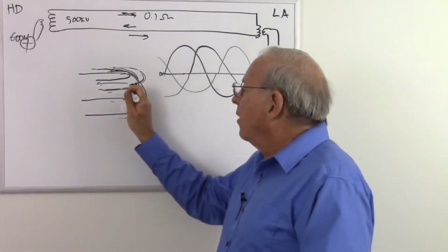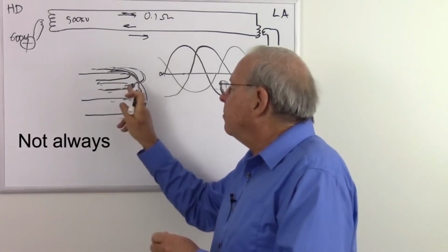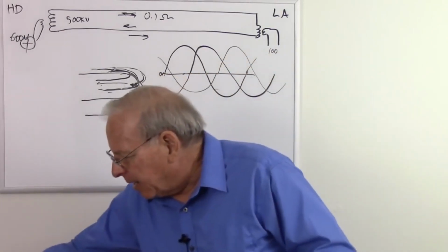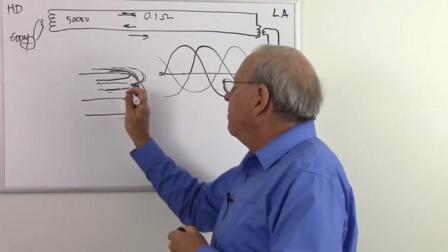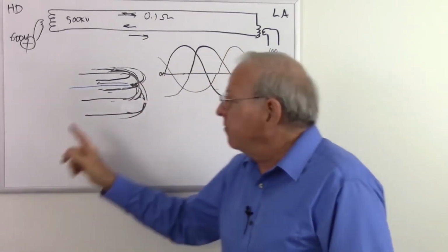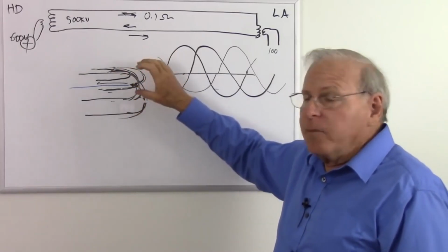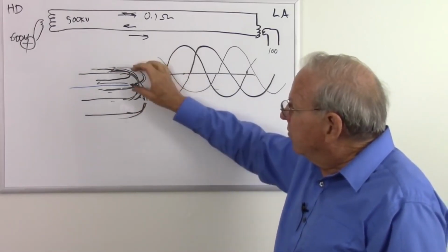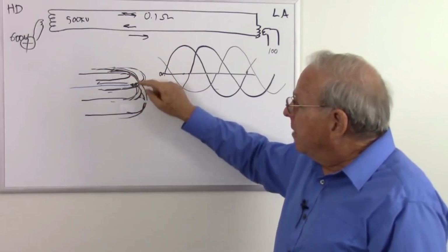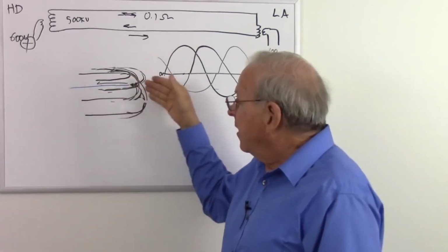Now there is a 4th wire. I'll put it back here, but I'm going to put it as a, well, probably should put the blue marker back in there just to remind us that it's different. And the main thing is that it's a much smaller wire. We need to have a little bit of a return, because if these are not being utilized the same way, if we're taking more power out of this phase than that phase, then there will be an imbalance. And so we need to have that return wire for the little bit of imbalance that we might have.